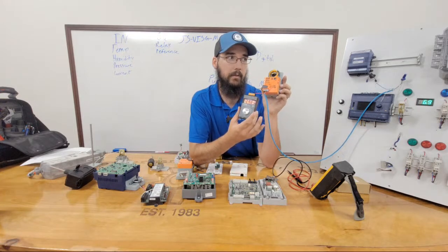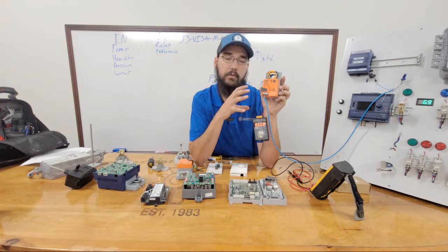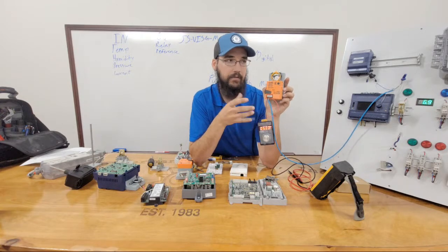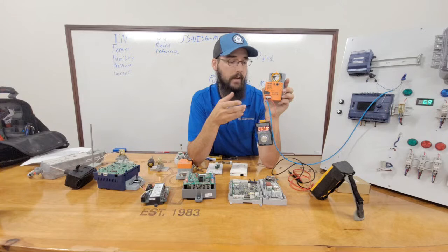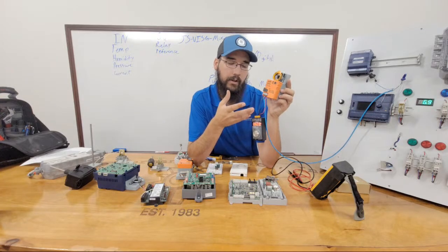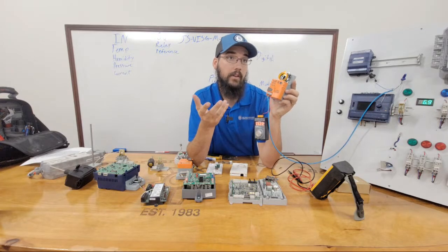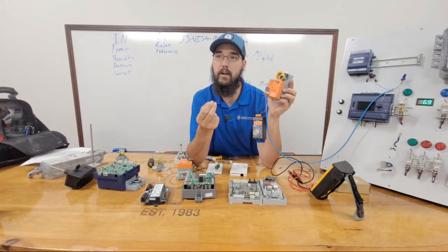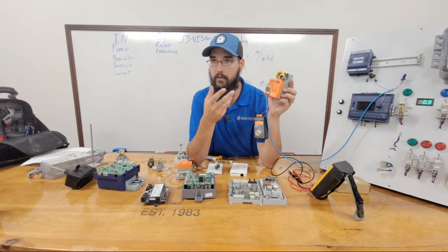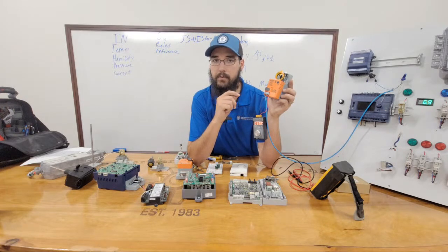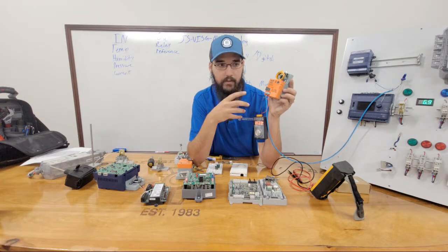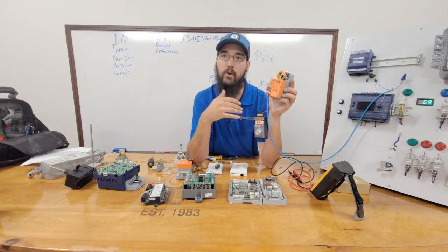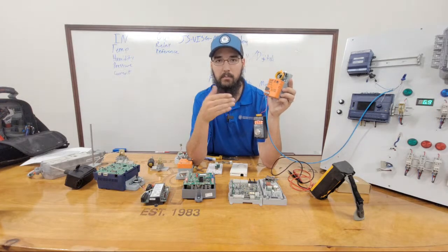These things can be really handy in troubleshooting actuators. So I highly recommend everybody have some kind of a signal generator. Ultimately, the alternative, say you didn't have this, then you've got to have some form of way to work with the building automation front-end system. You get into the computer, be able to override that, whether they have a remote ability, or you got to call the engineer on the phone. However it is, it's just a much bigger pain.